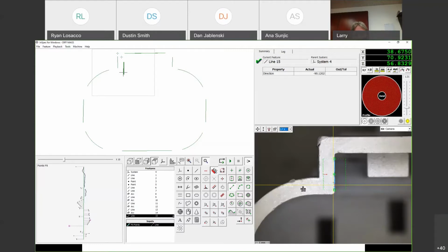Back, I believe it was maybe October, I did an hour-long lighting webinar. If you missed that, let me know, because there are a lot of lighting tricks for highly reflective parts and clear parts there. So here, the easiest way that I describe which way to do the red arrow is whichever direction has less noise. When I mean noise, it's that gray value.